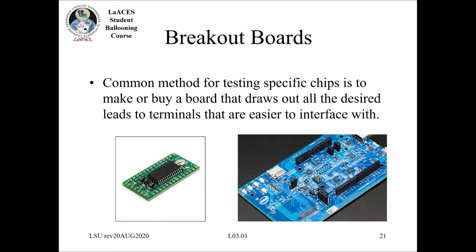So breakout boards, this is a way that you can have a little surface mount board, but then you can hook it up to your larger circuit or to a development board. Like on the right here, this one looks like a development board to me that you can buy, and there's probably some little things you can test on here. Like a vendor that makes these IC chips, they want people to use their parts, so they provide what's called a development board that already has a nice layout, and you can test all the functionality of it. And then if you want to add things, you can do something like on the left, where this might just be something that's kind of generic with all these different hole patterns, and then you can solder wires from the two boards together to get what a final circuit might look like, that you then take that design and do a full board layout on it.